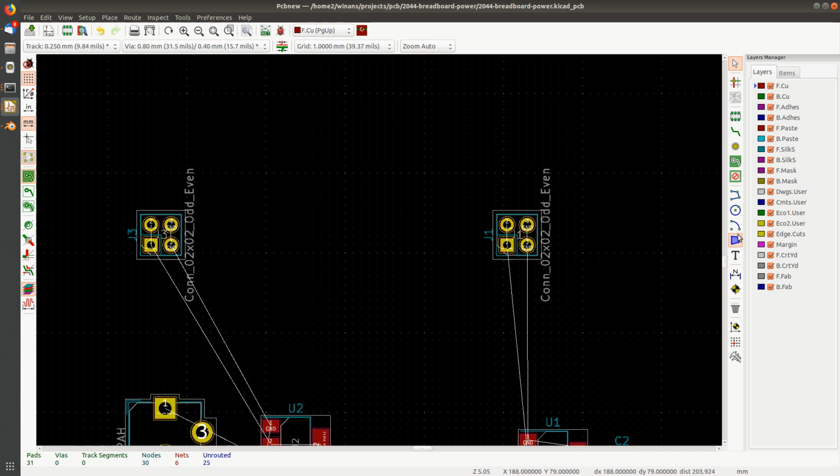But I don't want them to put this dimension drawing in the middle of my copper or on the silk screen. That's just for my own reference. So this drawings user or comments, these extra layers in here, are specifically intended for my own notes and annotations. So I'm going to select drawings user, this little arrow right there, and then I'm going to come down here to this draw me a dimension thing.